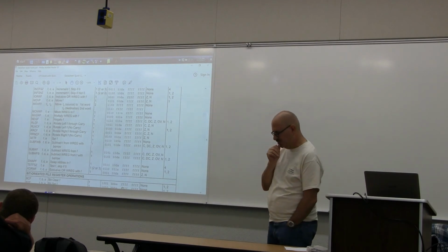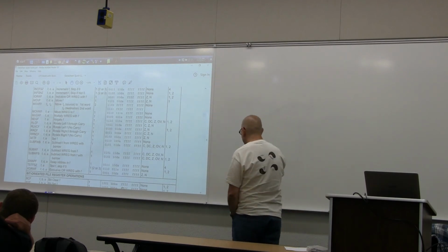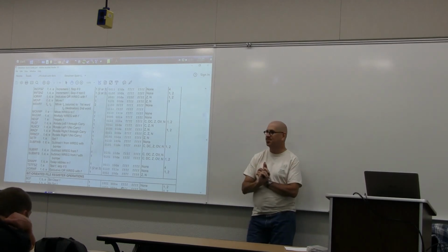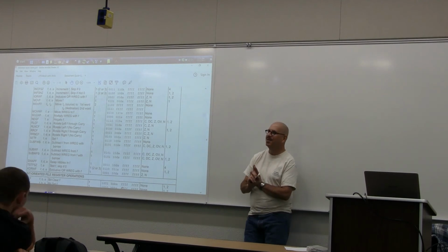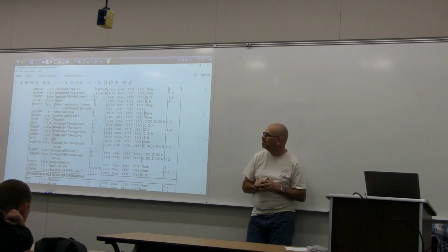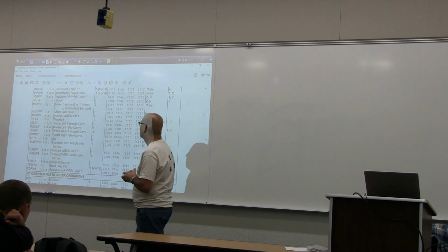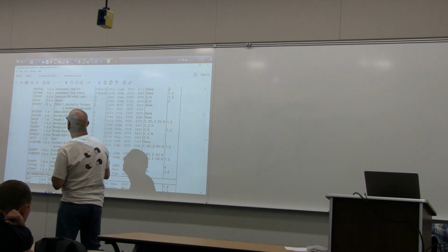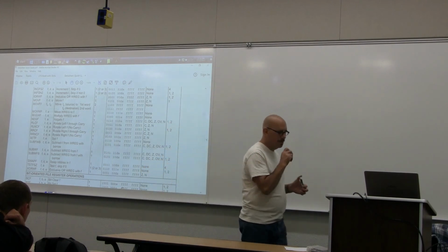Well, like all these other instructions, move can be told to assume that one of the registers you're working with is the working register. So if you have a number in a file register and you want to copy it to the working register, this is what you use. You say move file register whatever into the W register. All right, that's enough of those.